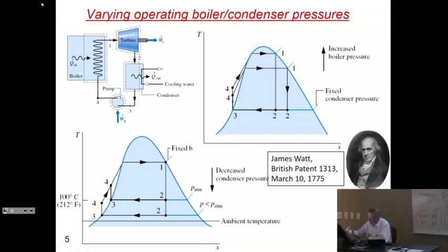Because now, if you can say from this point, you were going here, here, here, here, if you could get to a condenser that works under atmospheric pressure and at lower temperature, for example with water cooling, then you add yourself this much area, and in fact you have a net gain of area. The reason is that, again, the shape of the vapor dome is such that you have made the base wider here. The other thing that you have improved is the Carnot efficiency of the whole thing, because you go from a hot temperature to a colder temperature that is lower.